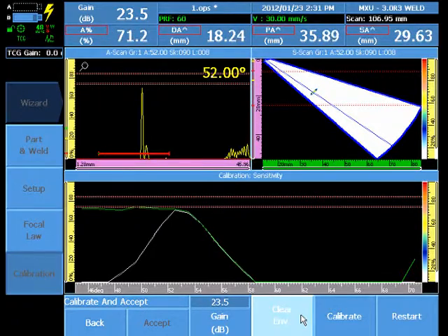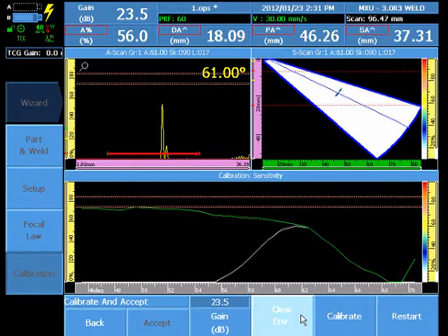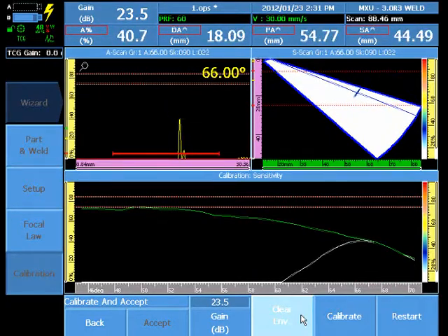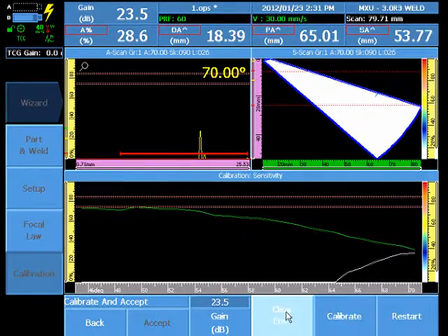every focal law after creation of the amplitude trace. The software is going to take every focal law and calculate the required dB to add to the general gain to make every A scan in the group 80%. Select Calibrate